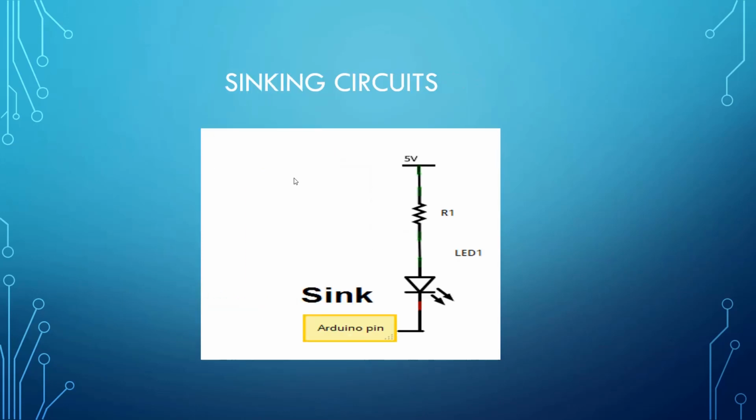Then another one is the sinking circuit. Here the microcontroller or Arduino is sinking the current, which flows externally to the ground. So it is called a sinking circuit.